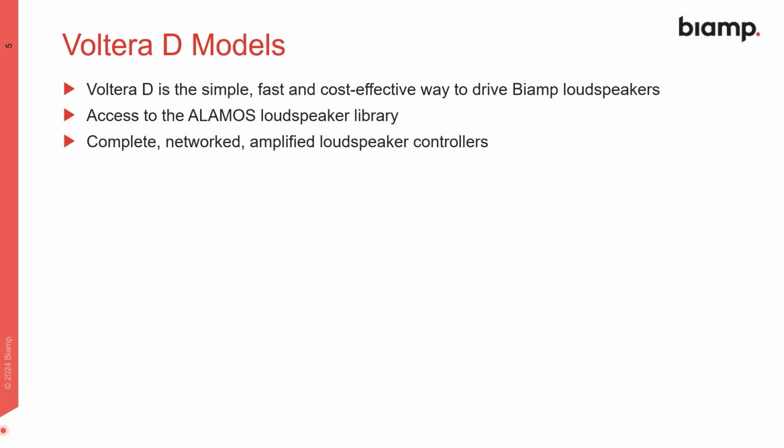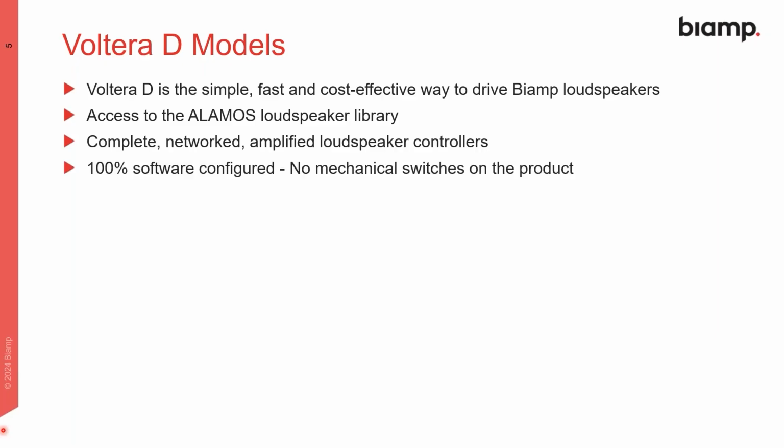We can choose different high passes, different low passes for full range and subwoofers when they're integrated together in the same project to perhaps save you some time commissioning. And we of course provide all the tap options for loudspeakers which are transformer based. So this allows you to easily recall optimized presets with protection, limiting, equalization to ensure your deployed systems are operating in the optimal manner.